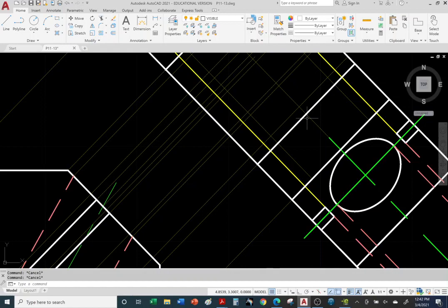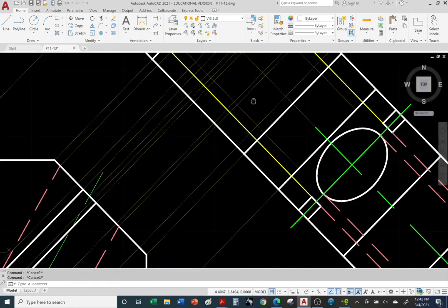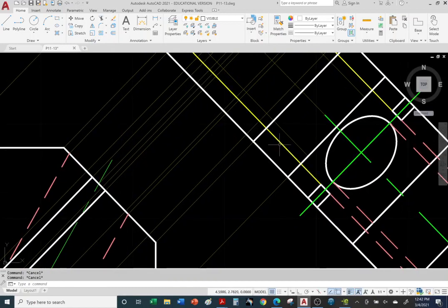All right, so these thicker yellow construction lines tell me the depth of the slot, right? Okay, so I need that so I know how far to go with the slot as I project. Okay, so we are in the visible object layer. Okay, use the line command, and here's the slot, right, from the front view.